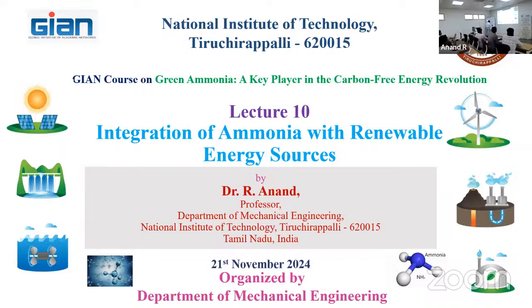So we need a work producing device called a turbine. A turbine is an expansion device where you are able to reduce the pressure from high pressure to low pressure. So we need to ensure that the organic fluid is entering at some desired pressure. So you are going to produce the work output. If you connect the turbine shaft with the generator shaft, you are going to convert it into electricity. Then, as per the second law, we are providing the heat, we are producing the work, the turbine, work is coming out.